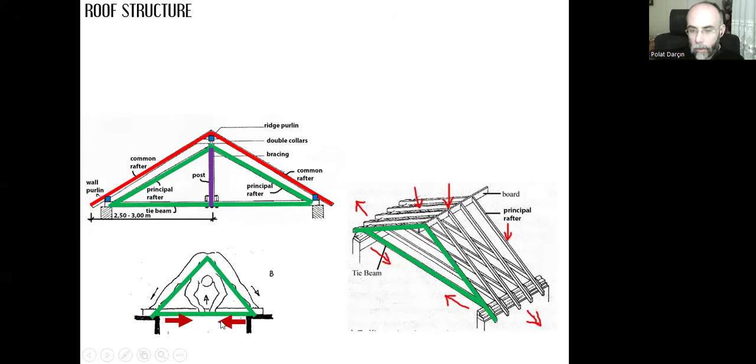And you just imagine that he is holding that horizontal piece with his hands upwards. He's lifting the middle part of the piece upwards like that. And that will create the fourth vertical piece like this. And the loads will be transferred upwards, and through these inclined pieces, the loads will be transferred to the structural system.